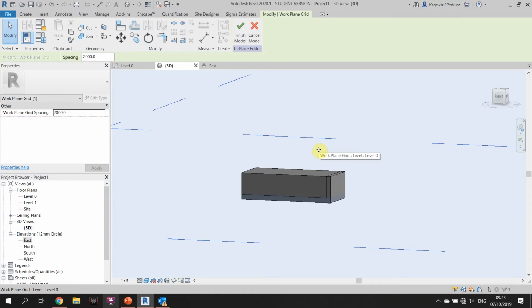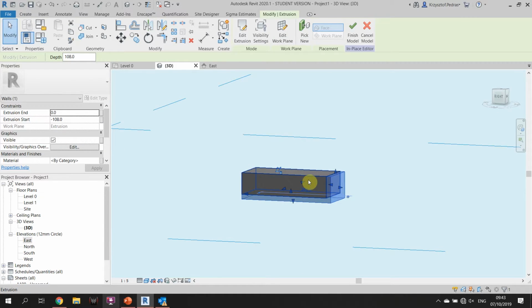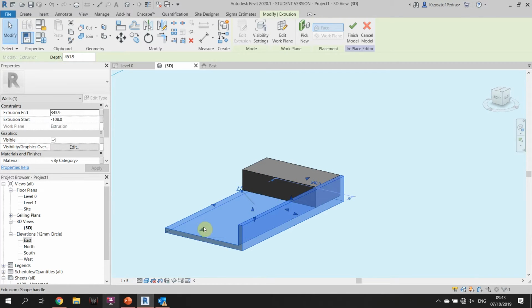All right, so we got a brick with mortar, but it doesn't really look like a brick. Are you still in that place? I see. Okay, so how to make sure that it's with the faces of the brick? Okay, so in the 3D view, you have those handles, right? You can see those blue handles. You click on the handle and then you can move it.